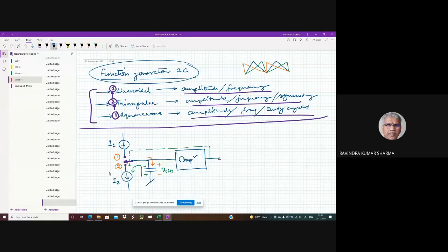The voltage at the output of the comparator will actually be a square wave of different duty cycle depending upon the type of symmetry that we have chosen. With I1 and I2 we decide the symmetry, okay? And then accordingly you have ramp generators here across the capacitor. So maybe this type or maybe the other symmetry, which is this type. Correct? So two types of waveforms are generated.